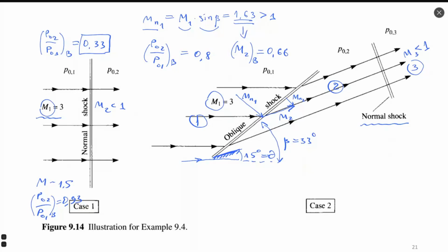Pay attention, because in your work one you calculate everything using formulas, since a formula exists for this calculation, and I use just the appendix to calculate fast. Pay attention that this value Mn2 which you receive after the oblique shock wave should be subsonic.